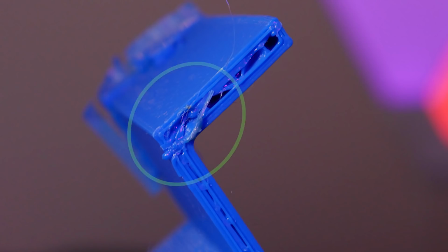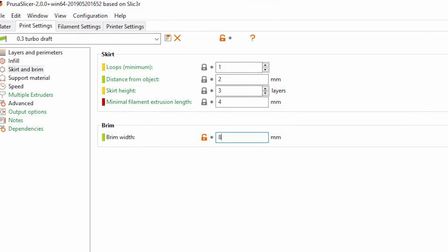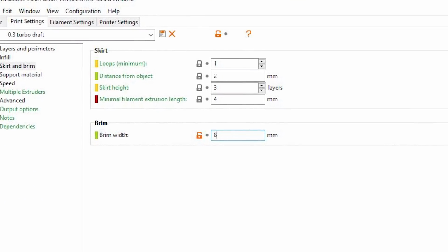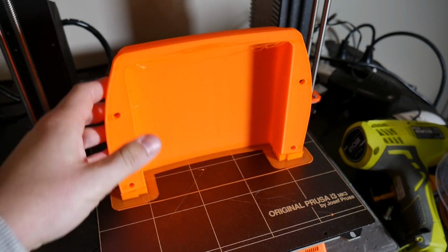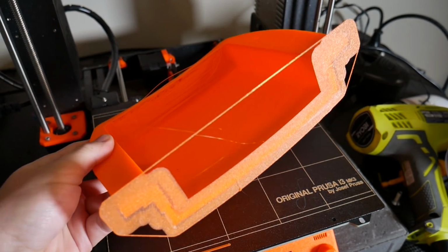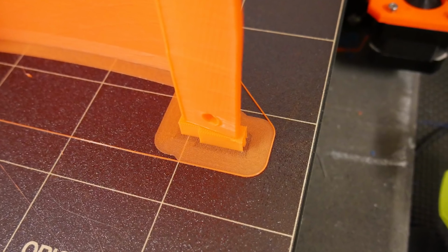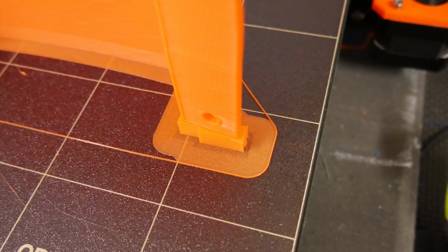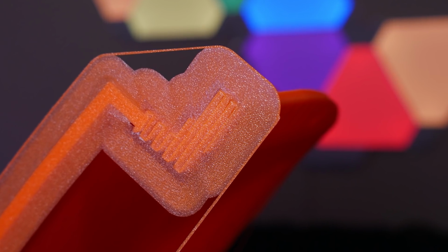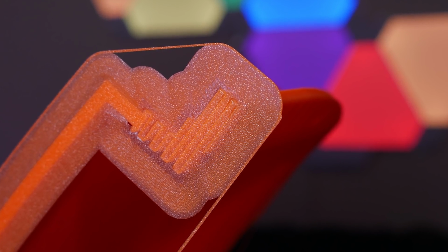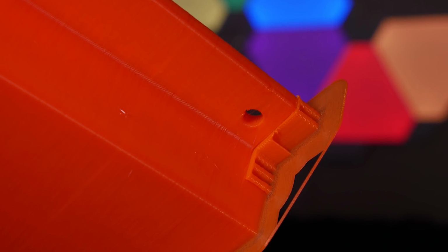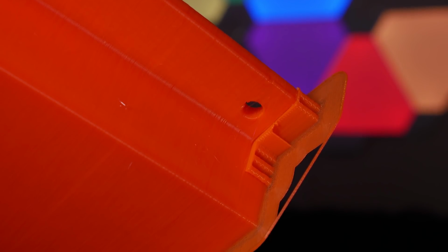And you can actually see where the nozzles caught on the part and popped it free and then just printed in midair with this part broken off. So what I ended up doing is going back into the slicer and adding a brim. Now a brim gives you extra bed adhesion and you just have to break it away afterwards. It's only used in the first layer, and I added an 8mm brim around the whole part because it is very thin and this is only one layer thick, so it just peels away afterwards. But you do need to remove it, and it made a substantial difference.